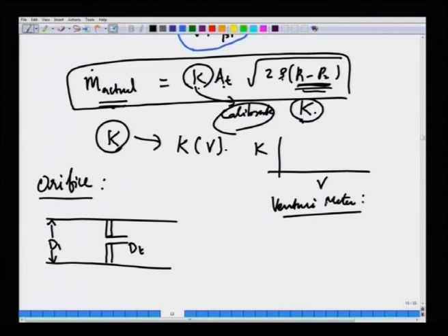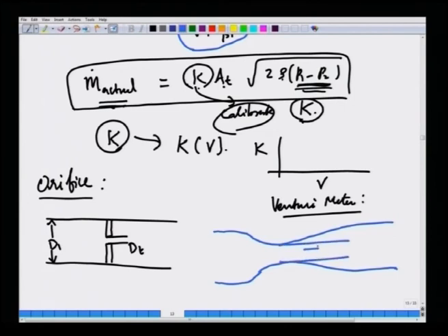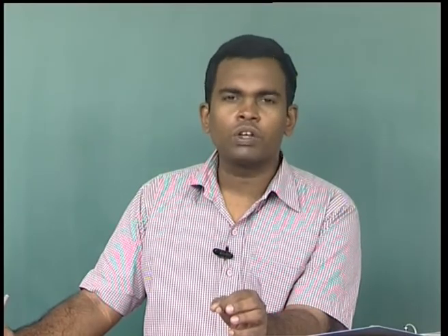Okay. So, here let me draw it with some other color. You have this upstream tube, but it gradually converges and gradually diverges, okay, and again fluid is flowing in this region like this. So, this is point 1, this is point 2, this is the throat diameter. Okay. So, these are the two common configurations of the restriction flow meters that are often used.